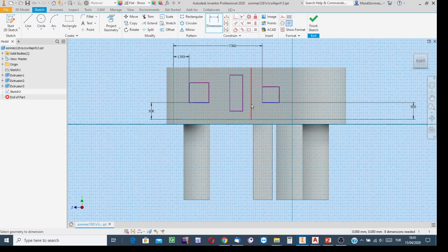These are anchoring distances. Well, for the door opening, its lower boundary and the edge of the floor should be 0 millimeters away. And then size the door opening from this reference, using the same reference to the boundary of the door opening. Distance, let's say, is equal to 4,500.